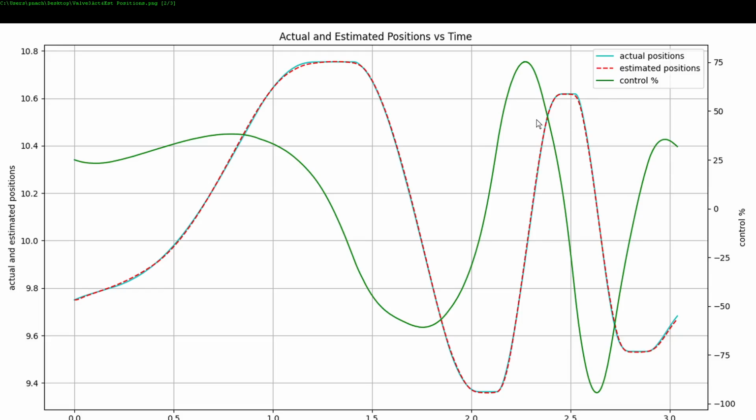So what you see before you is a swept sine wave, the green control line. And you can see it only goes up to 75%, which is going to be significant later. Anyway, you start out at a low frequency and a low amplitude, and it should increase. And then as you increase the frequency, you need to decrease the amplitude so that the velocity stays constant.